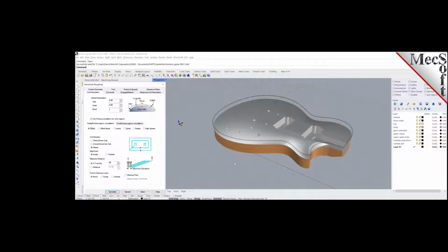But you're doing your roughing with a 0.6 offset, is that correct? No, I'm saying I'm leaving 1 millimeter thickness of stock, so I'm not getting any closer than 1 millimeter to the part. So that's the thickness I'm leaving. Okay, I follow you.